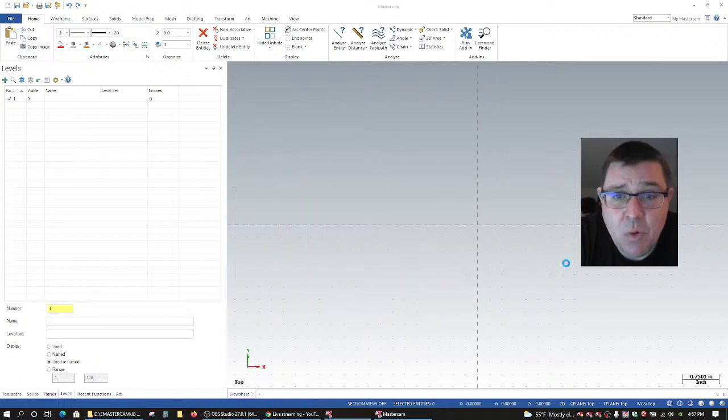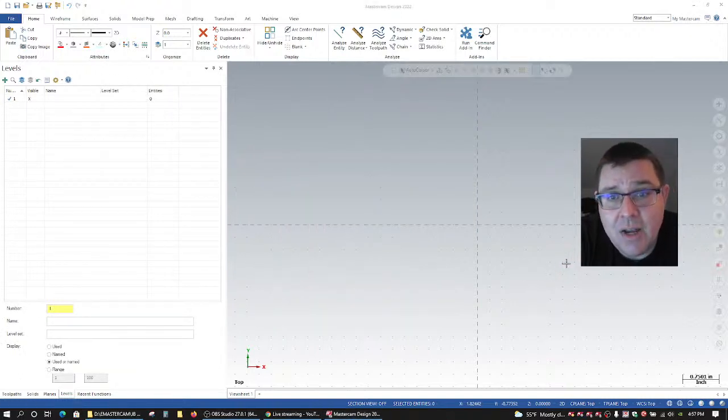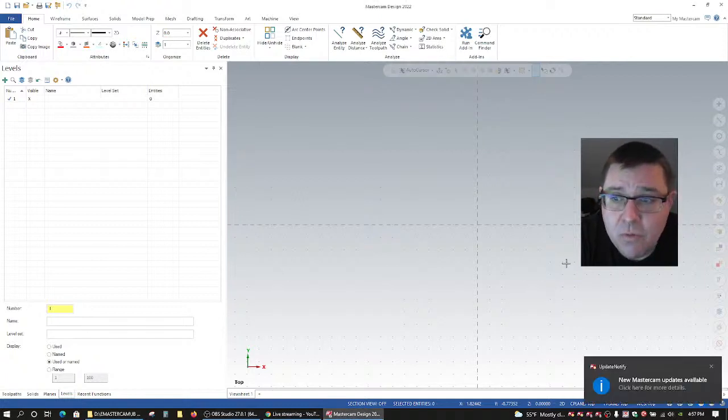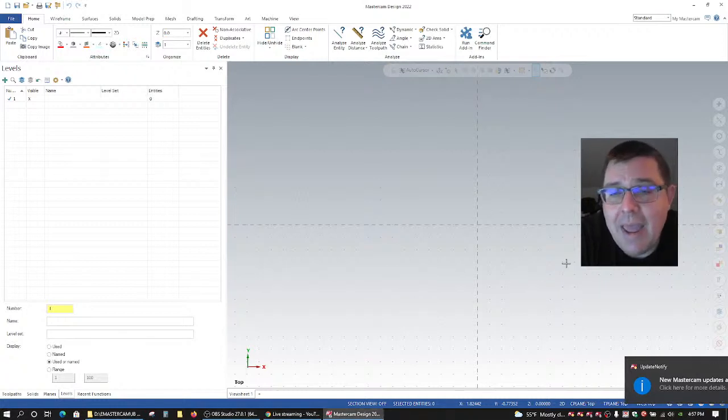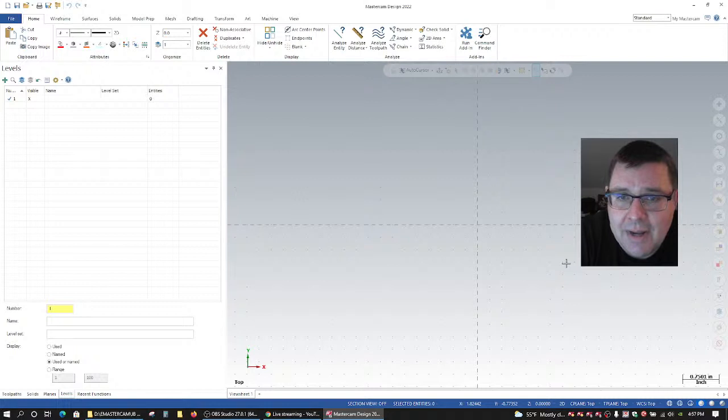The importance of removing history. So once you've got a model that you've copied, merged, moved, or repositioned, modified in some way, you can get some performance benefits if you do a remove history. So whenever I'm bringing in fixture components from another file and I've merged them in, I always remove history. I always delete the geometry group. So just some things that you can do to clean up your models.